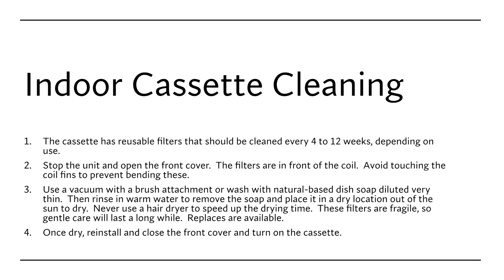Pull the filter out, and there's a little door, and I'm going to show you a picture here in the next slide. Basically, you lift the filter up out of there, take it out, do a little vacuum job on it, clean off any dust and other things that have collected on it, and then mild soap and water. So a little dish detergent, but diluted really thin. You don't need a lot of it, and warm water and a soft brush, and you can clean these up very well. Okay, then let them dry.